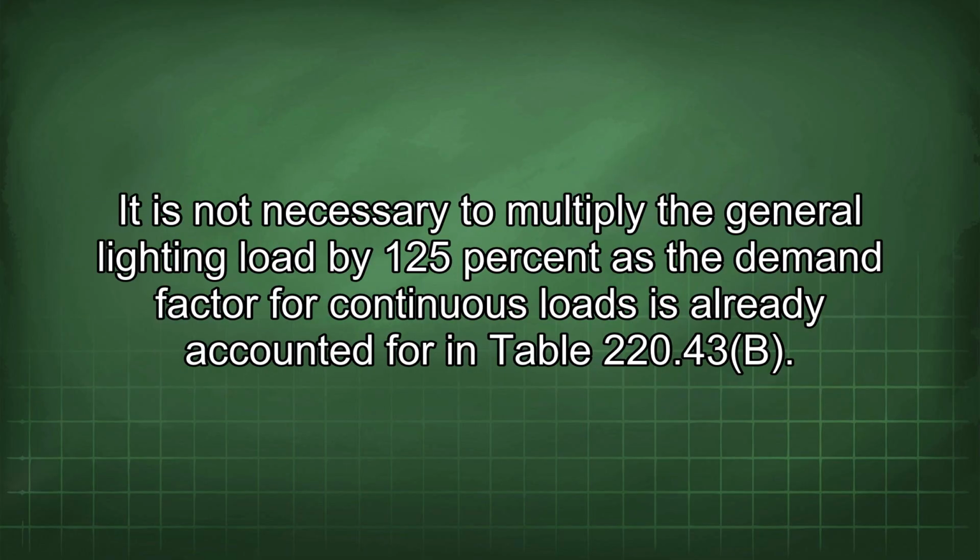It is not necessary to multiply the general lighting load by 125% as the demand factor for continuous loads is already accounted for in Table 220.43(B).